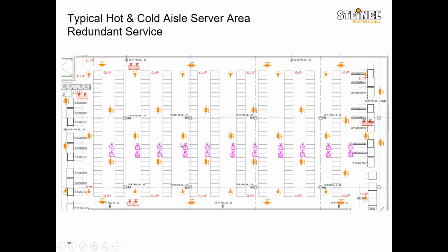And then you put a sensor in the middle, because this happens to be a very long one, and then another sensor at the other end. And notice that there's 2 TR150 power packs. Those 150 power packs are used in this case so that we can have an override switch to meet requirement number 3 of the code.